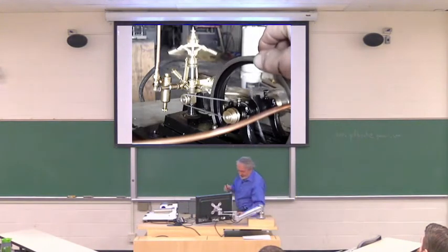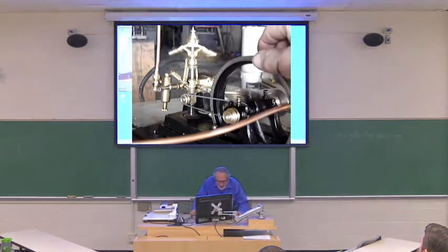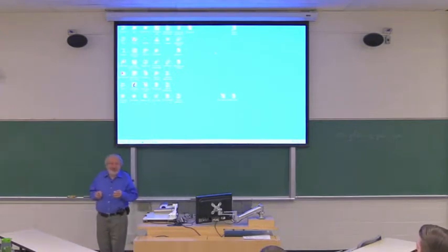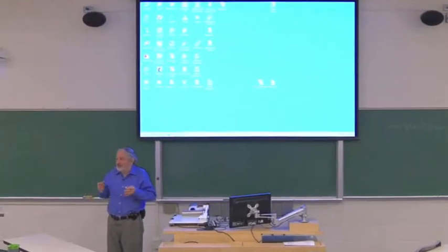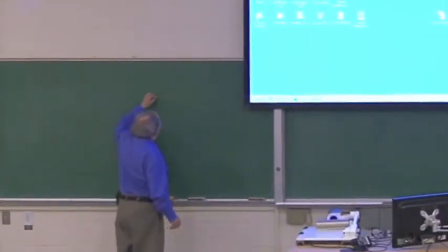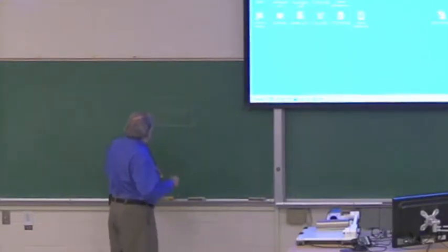You can stop that. Okay, so right after that, people became aware that you can do something called a servo, that you can use some set point to control a big thing called a plant. So you know servos maybe from electronics, but servos exist in hydraulics, in steam, in many things, not just electronics, and all they have in common the same thing. There is something we call a plant, even if it's just an op-amp, it's referred to as a plant.